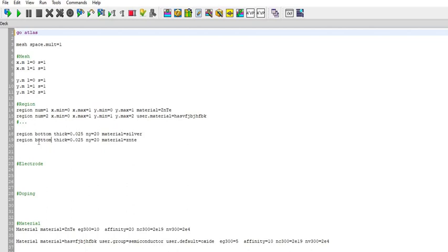And as I have given some methods, you can define a region as a conductor. You can define acceptors here also like 1E20, so you don't have to define the full doping statement. I will make a video on doping in two or three days. For a donor you can define 1E20 or something. You don't have to do that much hard work to write the full doping statement if it is a uniform one. That is the case.